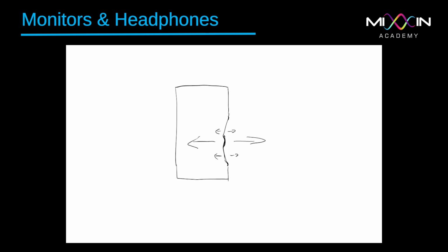So when the front moves forward, the back also pulls toward you, creating that same sound but in the opposite phase, which means it wouldn't be too much of effective sound because it would annihilate itself. We create a box around the speaker so that we don't hear this back movement, this back air pressure being created. Actually, it stays inside the box.